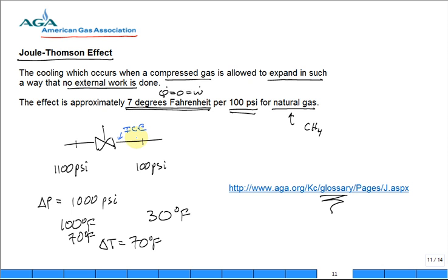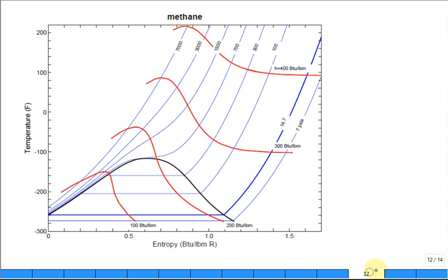Ice or some molecules acting like ice, and they could build up. Let's say you close that valve down, but it wasn't completely closed. A little bit's going through, and a little bit of water in it. Guess what could happen? It starts to deposit that water right there and build up ice, build up ice, build up ice. You decide to go open it, and you don't get the flow you got because it's plugged. Plugged with ice. It does happen, has happened. So this is one of those interesting applications.